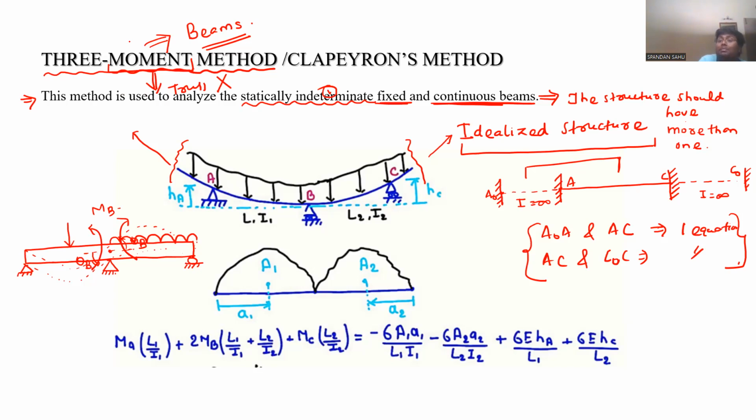Now, the slope-deflection method is a subset of the force method. In the force method, that is, the method of consistent deformation, we don't know which redundant you want to take. You choose your redundant in such a way that the structure becomes statically determinate as well as what? Stable. We don't know which redundant you want to consider; we only know you have to consider a redundant such that it should be stable.